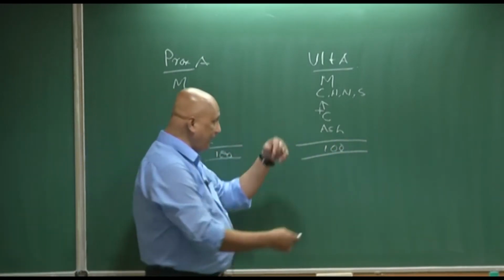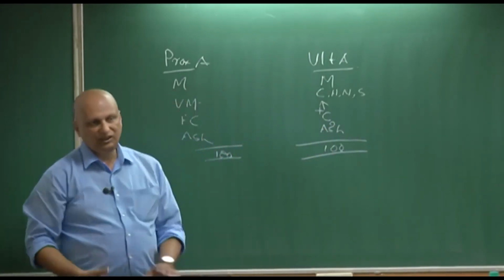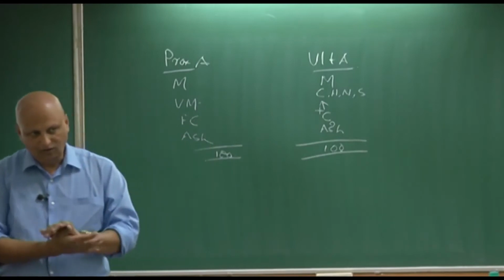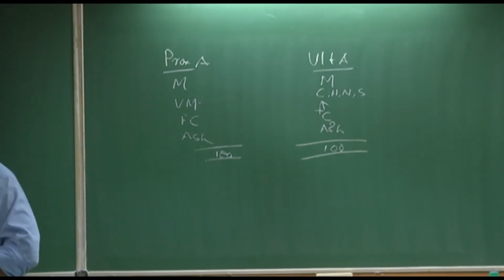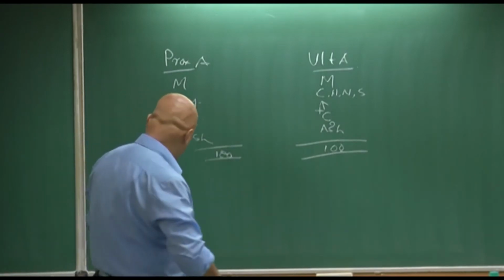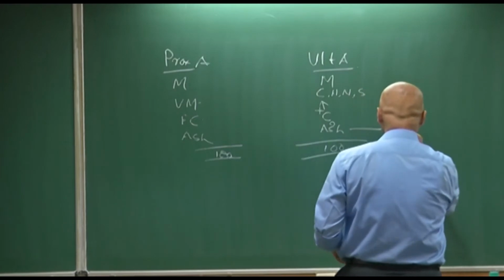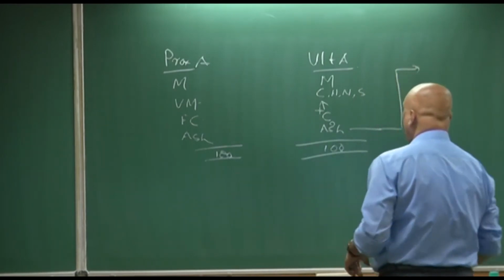And oxygen is by difference. Oxygen is not measured directly, it's all added up. So, carbon, hydrogen, nitrogen, sulfur, and ash are measured and then subtracted from 100 to give you the oxygen content. So, these are two very important measures, and then as I said before the lunch, we separately find